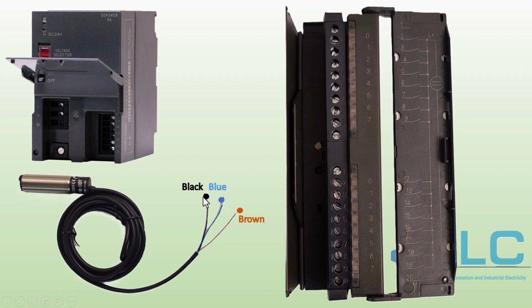Black wire. This is the output signal wire, which determines whether the sensor operates in PNP or NPN mode. I will explain this later. Additionally, some photosensors have a 4th wire, white, which is used to select light on or dark on mode. I will explain this function when working with real hardware, so we won't focus on it in this section.